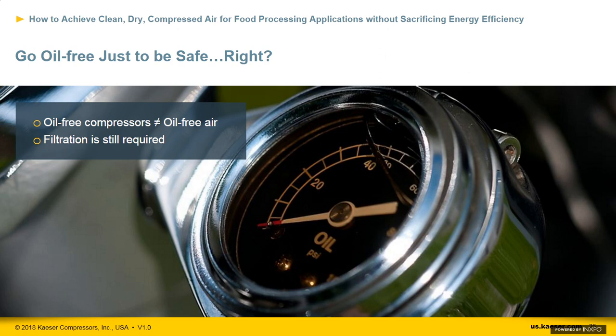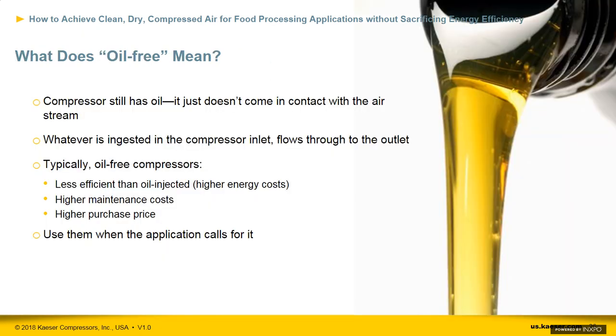Our last misconception has to do with the type of compressor selected. Oil is bad. Do I need an oil-free compressor? But just because you have an oil-free compressor, that does not automatically guarantee that you will have oil-free air. You still need to have adequate compressed air treatment to control particles, moisture, and hydrocarbons that may be ingested outside the control of the end user or the compressor manufacturer.